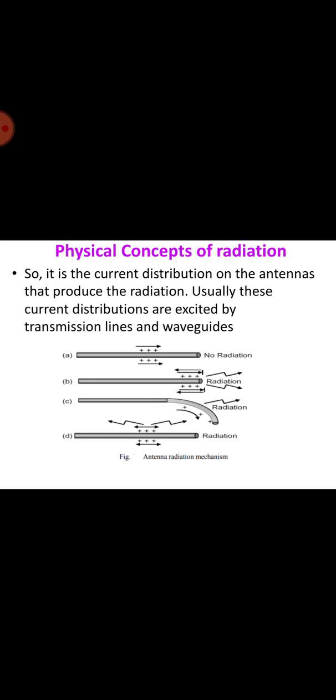In the transmitting case, the radiated power is absorbed by objects at a distance, that is, trees, buildings on the ground, sky and other antennas. In the receiving case, the passive radiation from distant objects or active radiation from other antennas raises an apparent temperature of RR. For lossless antennas, this temperature has nothing to do with the physical temperature of the antenna itself, but is related to the temperature of the distant objects that the antenna is looking at.